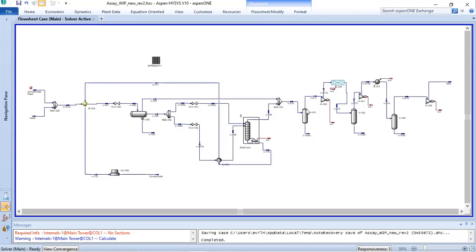And talking about the gas, it goes to a compressor. When we represent this kind of arrangement, it means that it is a compressor, a three-stage compressor, and we have aftercooler in the discharge of each stage to cool down the gas and prevent the equipment damage.